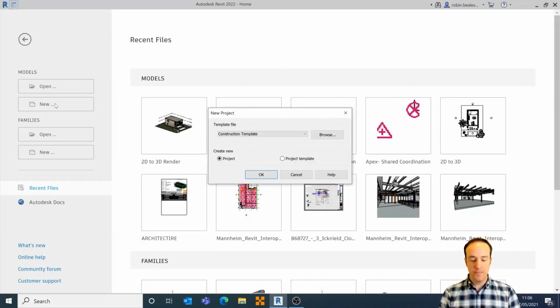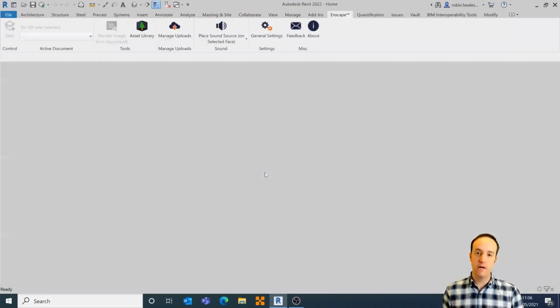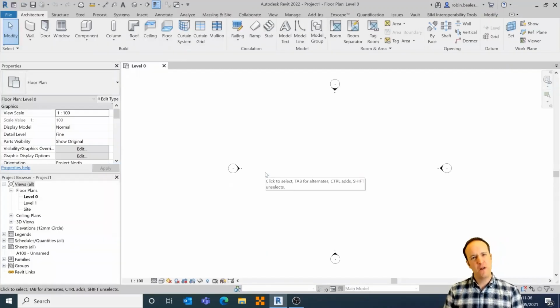So generally speaking, when we're working inside of 3D, the workflows are not dissimilar to what you're already doing in a 2D world. So, you know, when we're drawing a wall inside of AutoCAD, for example, either we have a block that we use, dynamic blocks, to bring it to life, or we're clicking a point, moving our mouse, clicking another point, and then doing some offset to add offset for plaster, offset for cavity, and so on and so forth. So the process inside of something like Revit is very similar. So what we're going to be looking at is that similarity, but then what you get off the back of doing it inside of an application like Revit.